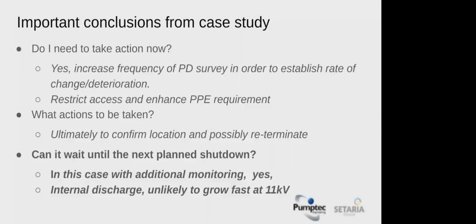Can it wait till the next planned shutdown? In this case, with additional monitoring, yes. The internal discharges are unlikely to grow fast at 11 kV, so time in this instance is on our side, and it could wait for the next annual shutdown.